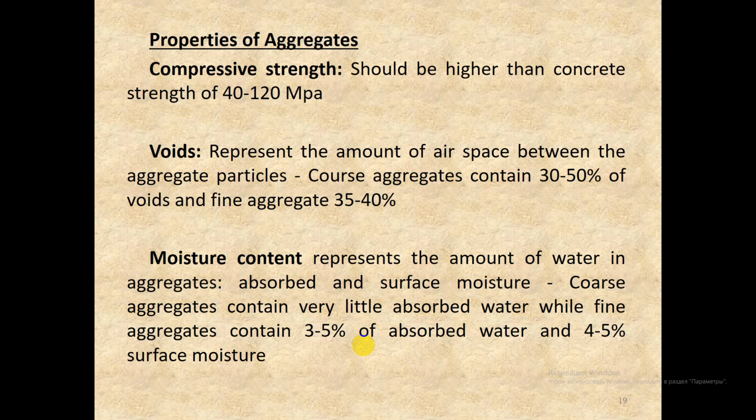Voids represent the amount of air space between the aggregate particles. Coarse aggregates contain 30–50% of voids and fine aggregates 35–40%.